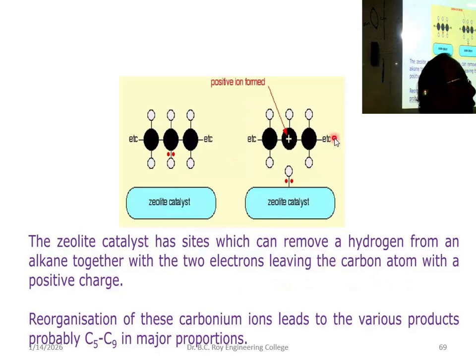Let me say how the bed is working, that is given here. Hydrocarbon is a combination of hydrogen and carbon. Some hydrogen is captured by the zeolite catalyst, and that way it promotes the breaking. Because alkanes are normally very, very inert. That you have heard in the class 9 standard. Isn't it? Alkanes are very, very inert, so normally they will not react automatically.